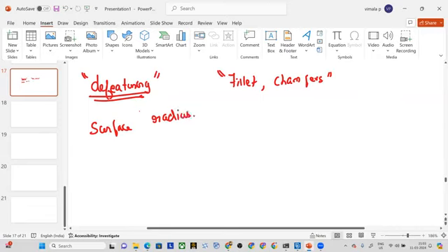Imagine you are dealing with a 2D component where there is a huge curvature of a surface which you have to remove, because without removing that, it will be very hard for you to go for the meshing process. Then you might remove some pinholes. We'll be discussing that in detail in the upcoming sessions. Then you might also remove some edges.